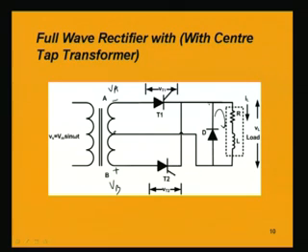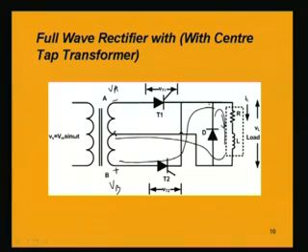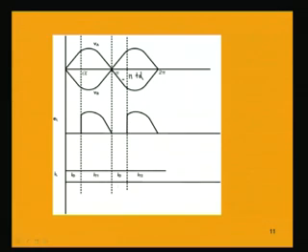So, when this thyristor T2 is conducting, the load current will flow from positive like this, through the load and into the ground. So, through the load the current flows in the same direction in both the cases. So, now the current in the load is due to the thyristor T2, that is IT2,